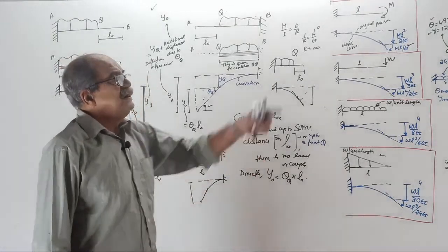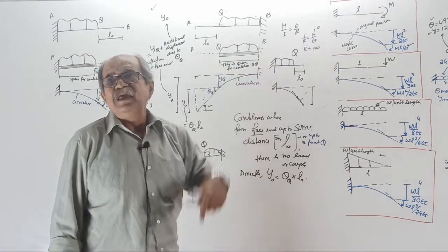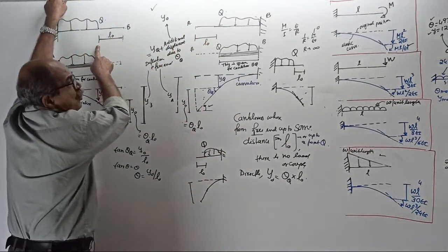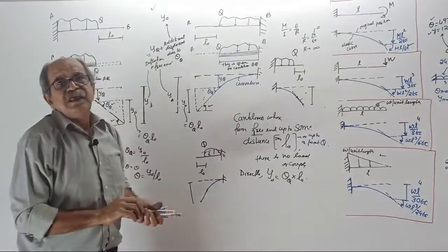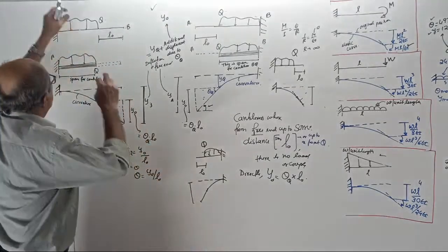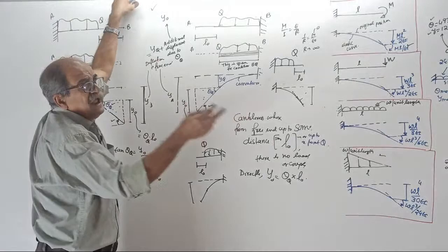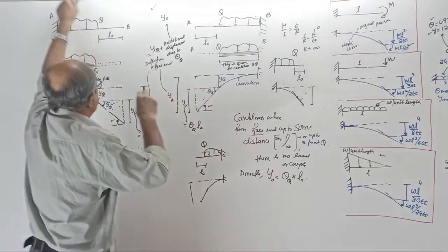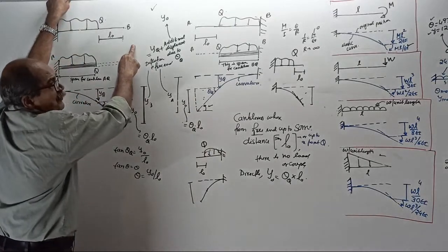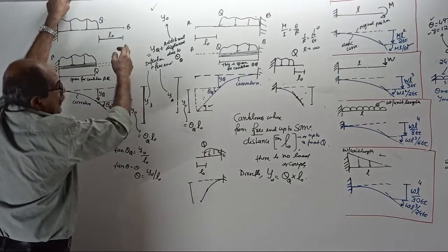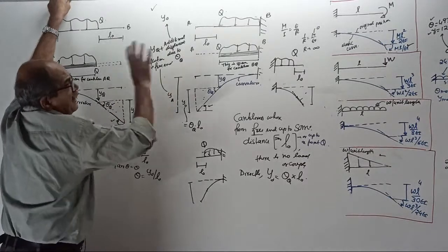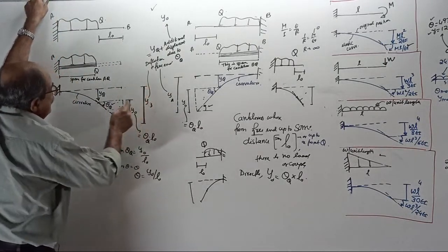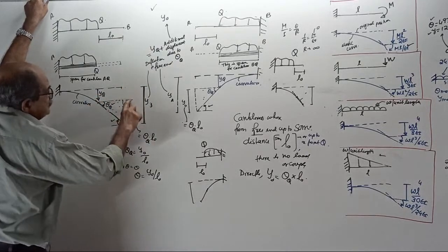Then the deflection at the free end equals the deflection at the point Q, where loading starts, plus the rotation at that point times the subsequent length L naught up to the free end. Up to anywhere, up to L naught, both cases. Therefore, the total deflection is this already, y Q plus y naught.